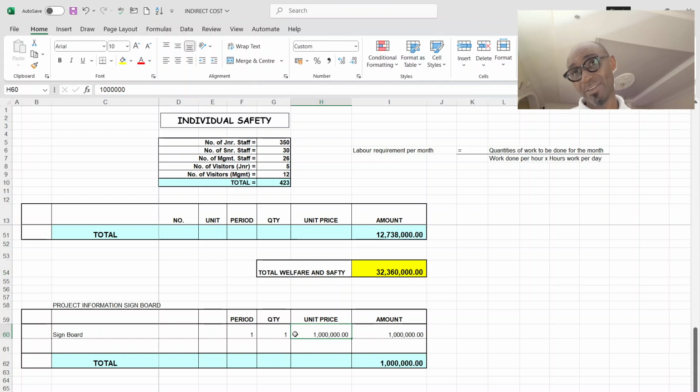If you know the kind of materials, the kind of sizes of pipes that they needed, you know what the cost is, you know the height, you know the plate, what thickness of plate. You, as an estimator, you should be able to estimate everything. Electrode, how many pieces of electrode you can use to weld this and all of that. You need to know how many grinding discs, how many cutting discs you need. You can estimate this to know the price. The only thing you cannot estimate is the printer that will engrave and all of that. That is a specialist work. He needs to do that and tell you what it's going to cost you.